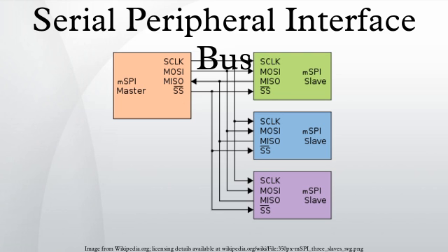With multiple slave devices, an independent SS signal is required from the master for each slave device. Most slave devices have tri-state outputs, so their MISO signal becomes high impedance when the device is not selected. Devices without tri-state outputs cannot share SPI bus segments with other devices. Only one such slave could talk to the master, and only its chip select could be activated.